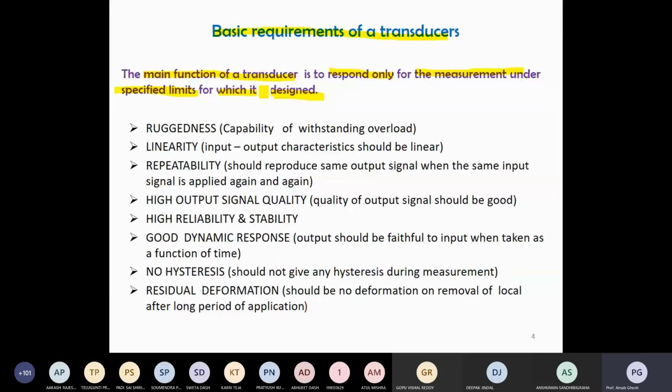So in that case, you have to design some measuring resistance. The calculation for the measuring resistance is given in the data sheet of your transducer model. So you have to calculate it as per that value, and insert that resistance to keep the current within the limit range. That is the first mandatory feature.